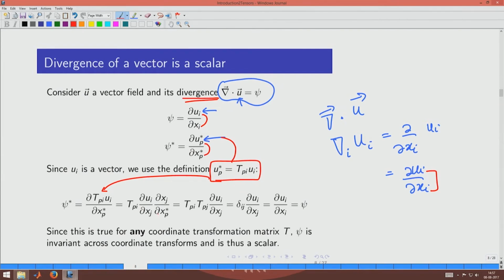So, when you bring it out, then you can see this expression, in which the second one is again familiar to us. It is basically nothing but the elements of the transformation matrix. So, then we have got two transformation matrices coming side by side. Using the subscript notation, we see that it is basically a summation over the first index, and we realize that there is a simplification we can do. The second indices are not the same, the first index is the same. So, we can put the second indices into that Kronecker delta because of the orthogonality of the old and new coordinate systems, and we have put that in here.